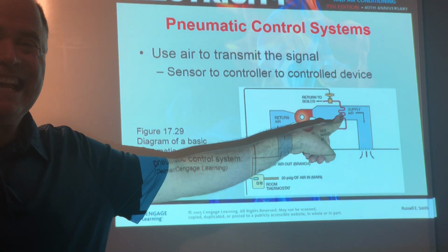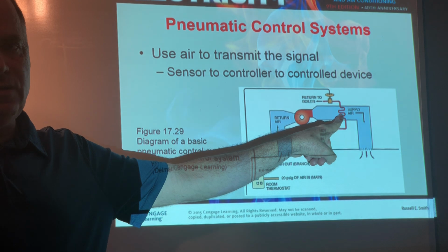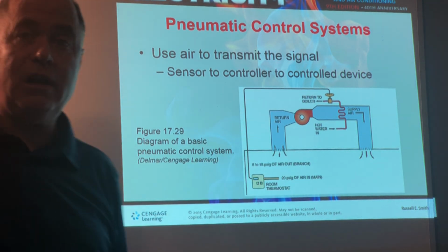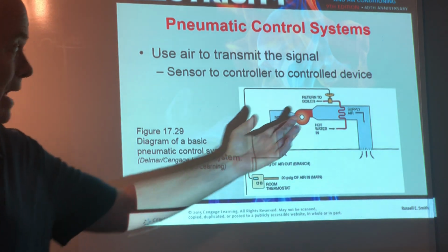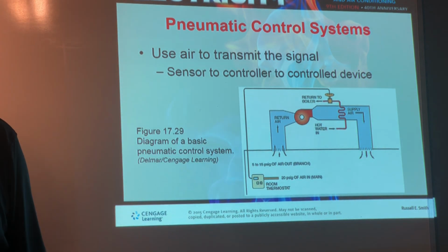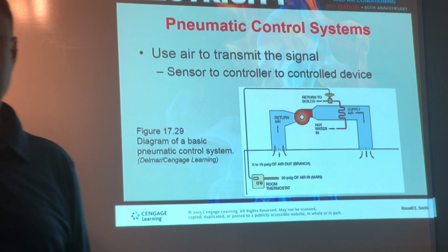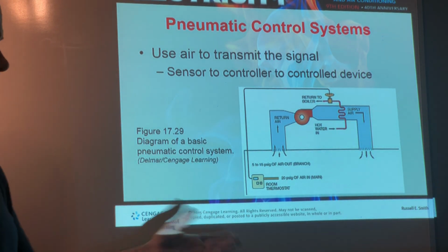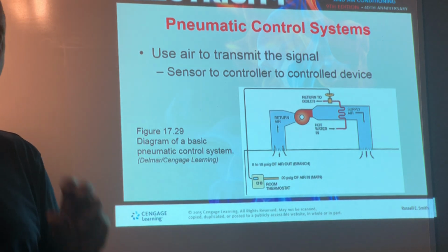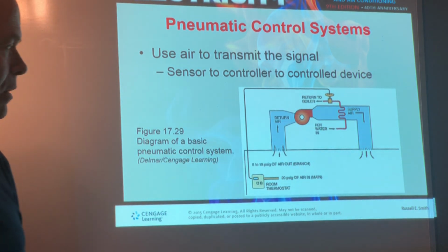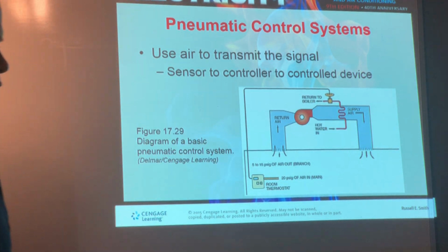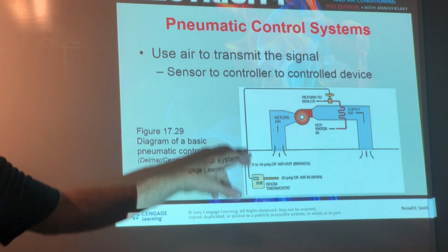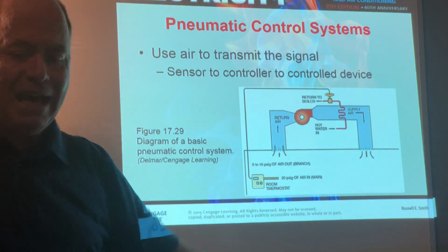Again, this might be 190 degrees, right? So this might be 130 degrees warmer than the room you're trying to heat. However, when you have chilled water, we're only getting 45 degrees, so that might only be 30 or 40 degrees cooler than what you're trying to cool. So you can see that you need a very small hot water coil, and that's why we can have a coil here near the zone, which is called hot water reheat. And here's the hot water valve being controlled by a branch pneumatic signal.